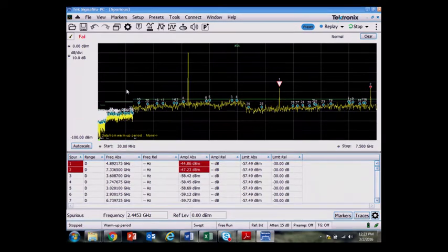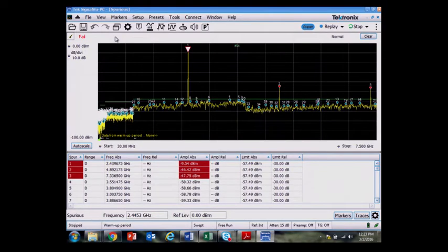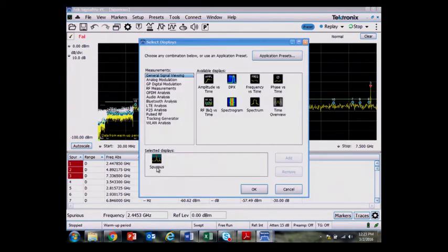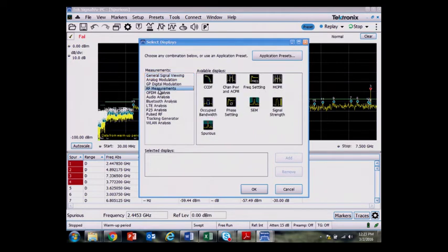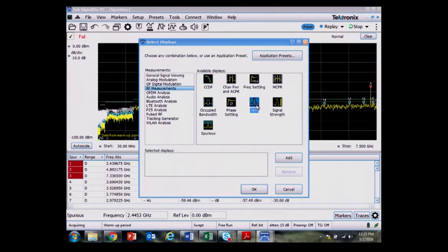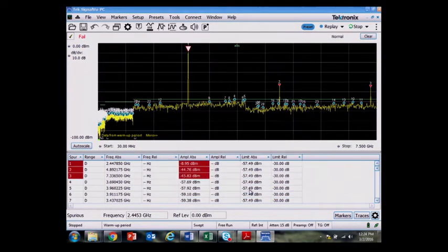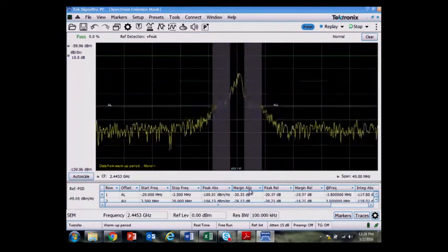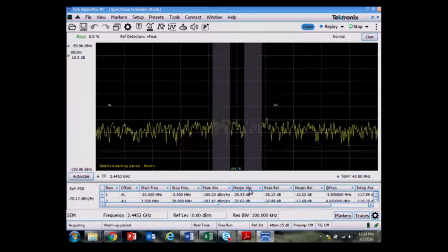Another part of radiated emissions tests are to look close in around the ZigBee signal in this case. The way that that's done is I'll pull up a spectrum emissions mask. So I go back to the RF measurements. By the way, both these features are standard free of charge options or capabilities that come with our USB spectrum analyzers with SignalView PC. Anyway, spectrum emissions mask is what's frequently called for testing close in EMI limits.